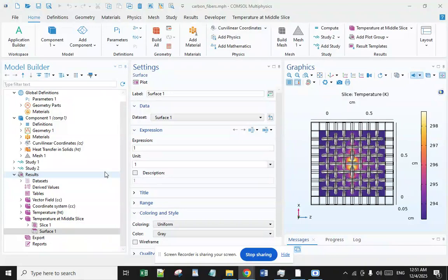The temperature images from the IR camera were video recorded at a frame rate of 30 Hz. All post processing was carried out using the FLIR Tools Plus software. The hot plate temperature was monitored using a type K thermocouple and recorded on a Pico thermocouple data logger for each type of fabric and conductivity measurement. Two or three repeat experiments were carried out.